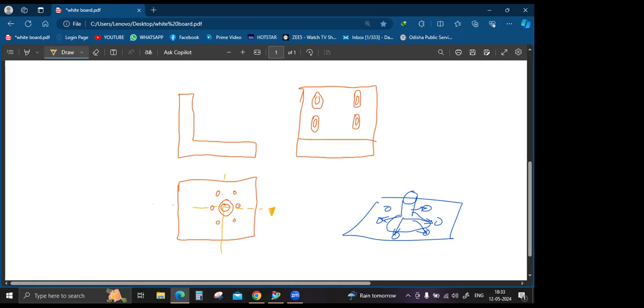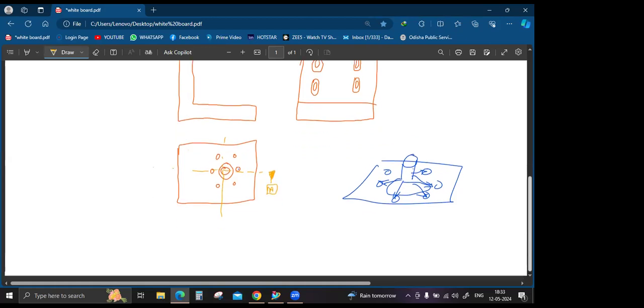This is my A. Okay, and this another vertical side I can provide, sir. This is my B. Okay, you understood? So from the A and the B, we can easily control the positions of these 6 holes. So we can easily give over here, sir, this is the position. Okay, with a very particular tolerance with respect to A and with respect to B. Okay, again, it is the wrong one.